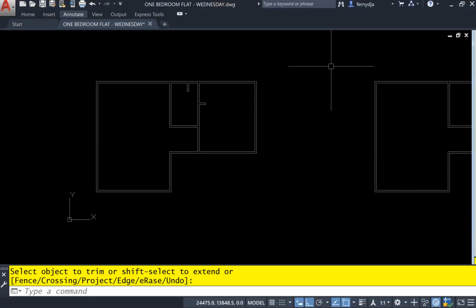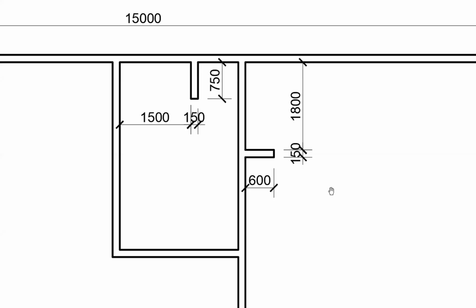Sir, what if it wasn't a closet wall? What if it was just a wall that would not be carrying load other than its own? Would we still have to dig a foundation for that? No, you don't have to. So some partition walls, especially if you're doing all like dry walls, don't need any foundation. So you just have your main walls that you have target and make those be the ones that have the foundation and those other walls.